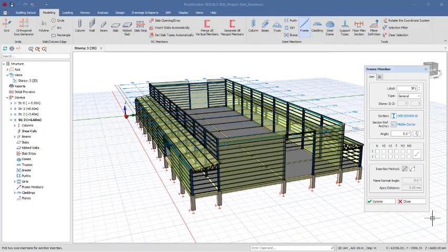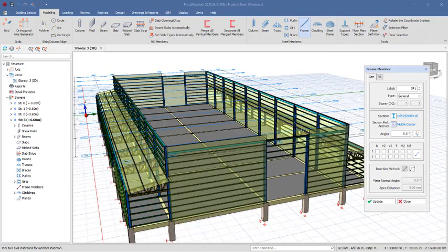After having this done, for me to have a curve over here, what I need to do is come to the insertion method right there, and then I will select the second method, curve insertion. Once that is selected, the plane normal angle is going to be 90 degrees, and then the apex distance, so this is the apex height of the curved beam rafter. I will get that to be 2500 just like this.